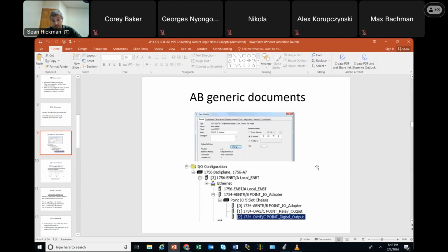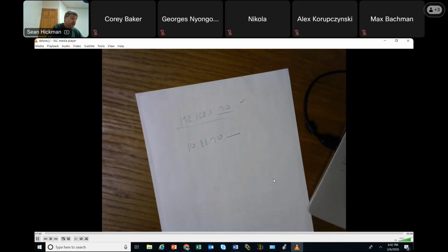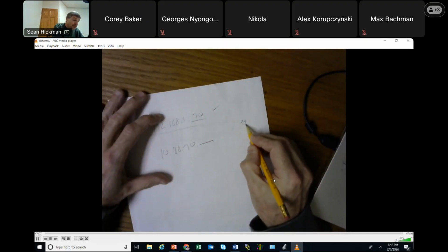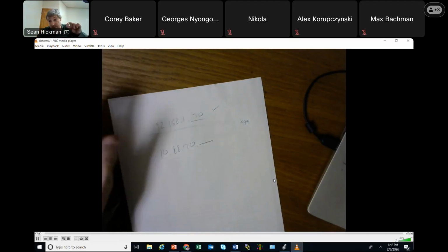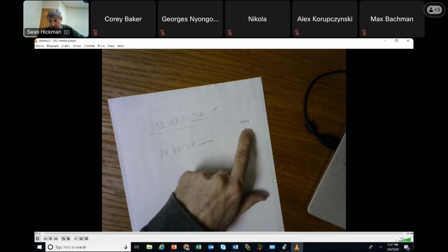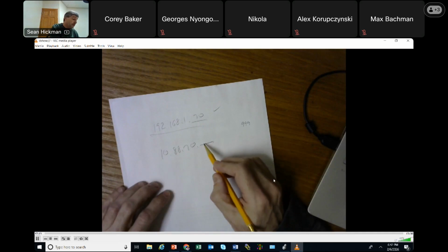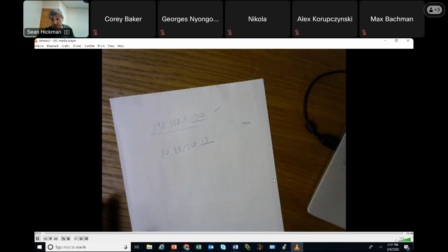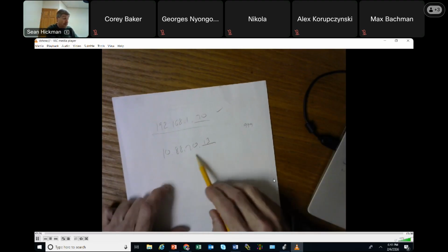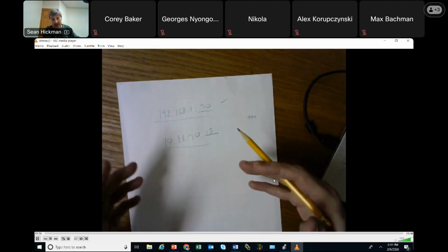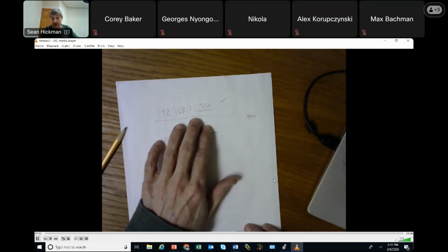10.88.70. something, if you want this to be your network, well, then what you've got to do is set that pinwheel to 999, or you could go into your bridge. Your bridge has got little pinwheels to set all the stuff, or you could go in and set it using USB to B, whatever. And then you could give it this network here, and then you could give this a number 13, and your controller could be number 14, and your partner's computer could be number 15. But there's a lot of different networks here, it might not just be this nice, okay?